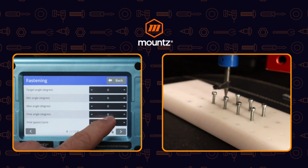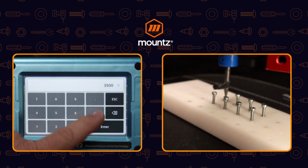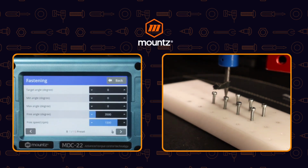And so this particular fastener is about 6,000 degrees of rotation. So let's go ahead and set this to 3,500 degrees of rotation, and we want to have 1,500 RPM for that portion of the rundown.